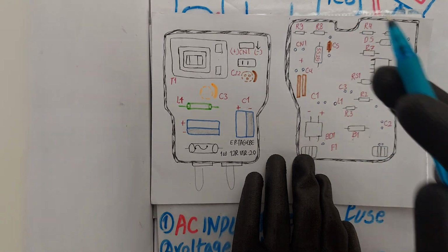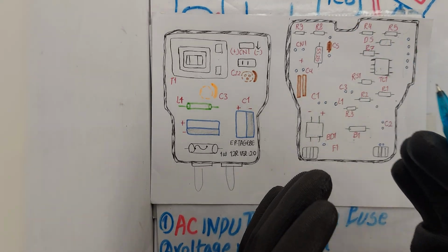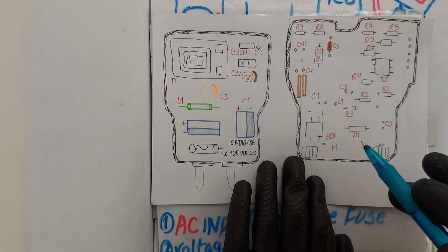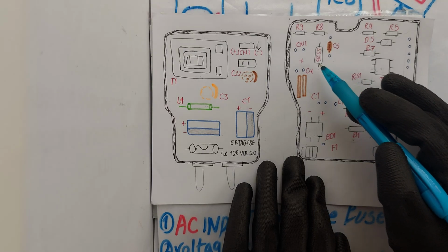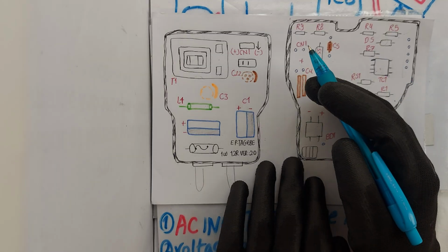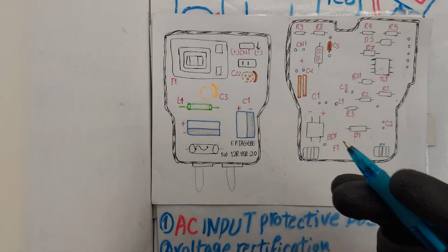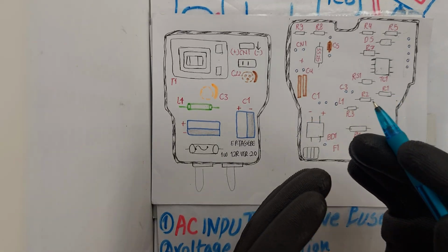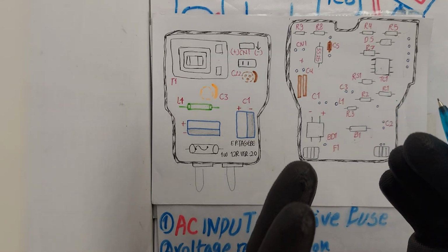And lastly, we have output protection. At the USB output pad, a resettable fuse, F1, or overcurrent protection circuits and a protection diode, right here, D6 or similar, are typically used to prevent circuit damage in case of a short circuit or reverse voltage from the battery to the charger. These safety measures extend the charger's lifespan under abnormal conditions.